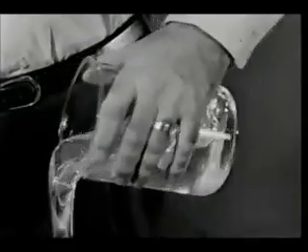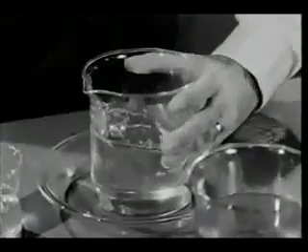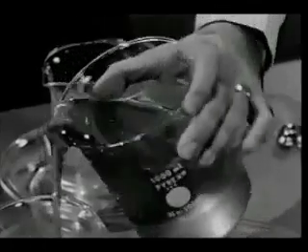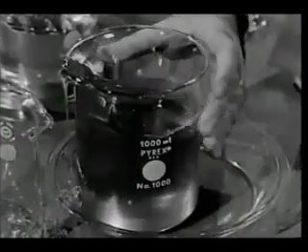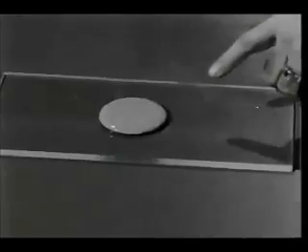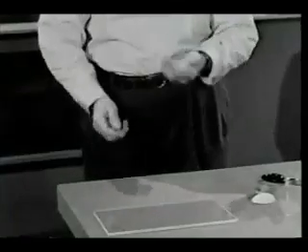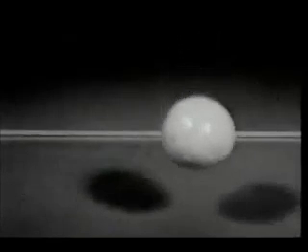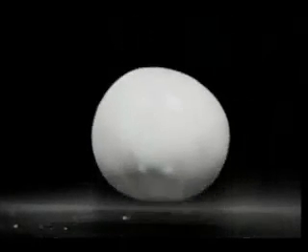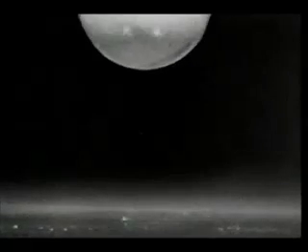This material exhibits both viscous and elastic characteristics. Honey has a high viscosity, but no elasticity. Remember the fluid ball? It was like an elastic solid during the short impact of bouncing. An elastic solid has a preferred configuration to which it will return when stresses are removed. A viscoelastic fluid behaves similarly if the stress has been applied only for a short time.